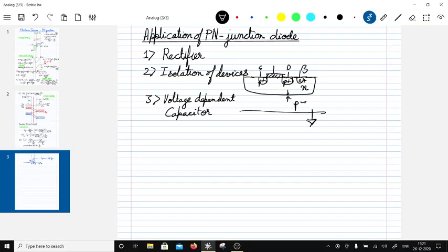Now another thing is in case of a BJT, you have got two such p-n junctions back to back. So let's consider an NPN. There is an NP junction, which is going to be the base emitter junction, and then there is a base collector junction, which is a p-n junction here. These back to back junctions, their properties are going to decide the characteristics of the BJT. So the injection efficiency of electrons over here is going to decide what the beta is, and then